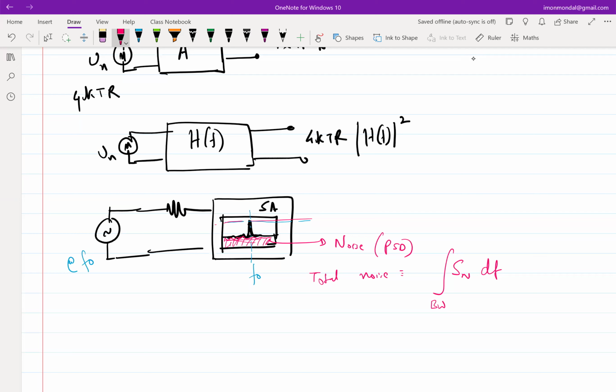In terms of communication, when you are communicating something, you would like to communicate in as little time as possible, right? Which means you need high speed, you want low noise, you want low power, and so on. So in terms of all these parameters, if you reduce the bandwidth, what gets affected? Obviously, noise gets affected, it reduces. What other thing gets affected? Speed gets affected. Naturally, bandwidth has a direct trade-off with speed, right?